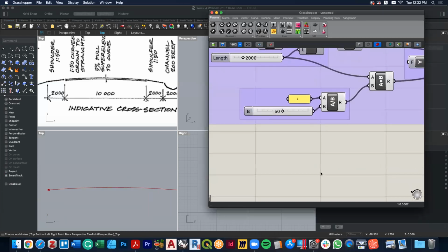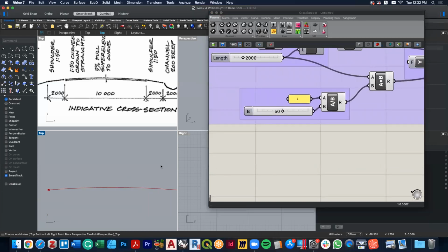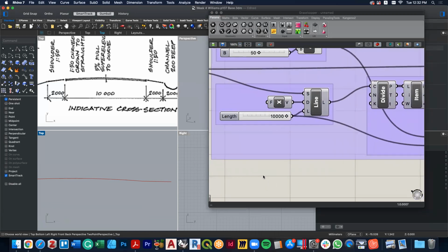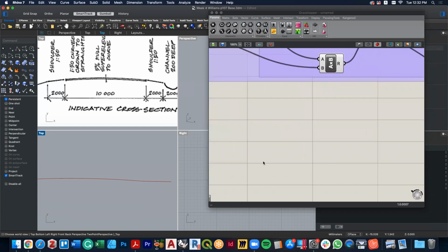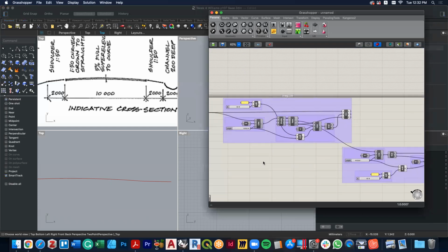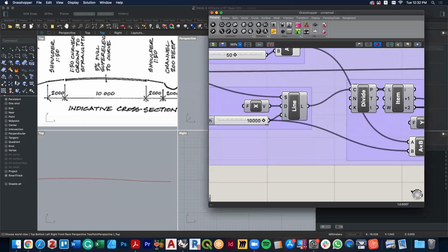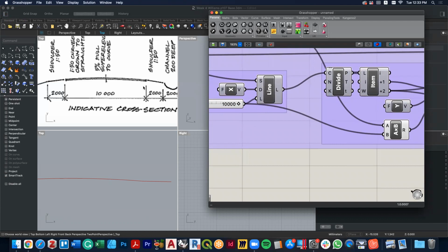Now, what do I have that on? And so, funny, it looks different, huh? 1:50, 1:50, you know, oh. You know what I've done wrong here. Interesting. Can you tell me what I've done wrong? I can tell you. That's pretty interesting. So obviously I've assumed here that my whole grade of 10 meters is falling down. But in actual fact, it's from the center line.